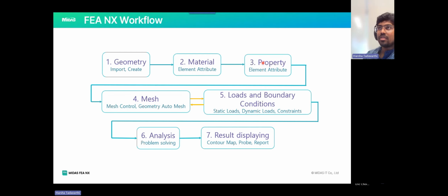Generally that might not be suitable, because plane strain condition works well for the dam, and the degrees of freedom of a shell element or plate element are different from those of a plane strain element. So hence the behavior would be different. The concrete gravity dam is mostly a plane strain condition. Hence, it's better to consider plane strain property. So we'll define the 2D analysis for plane strain condition for both concrete and rock here.